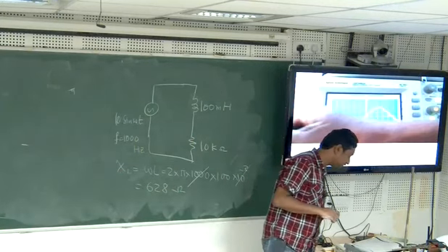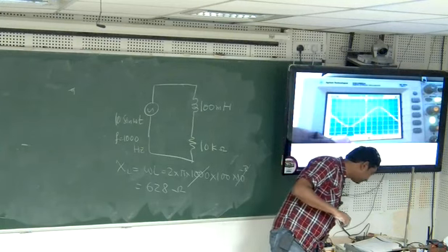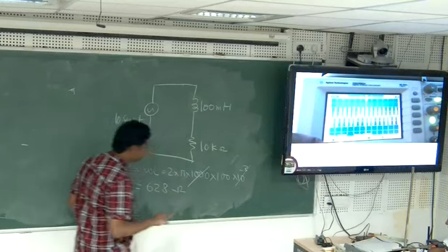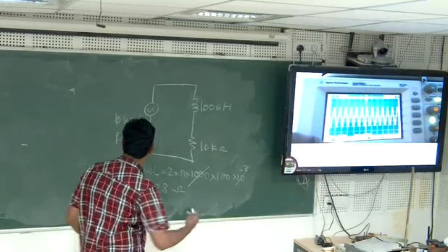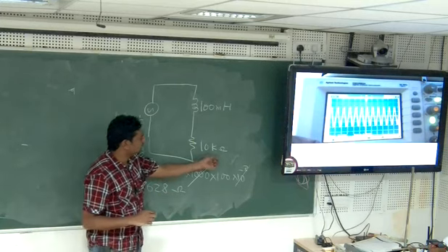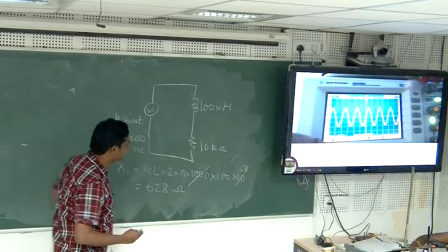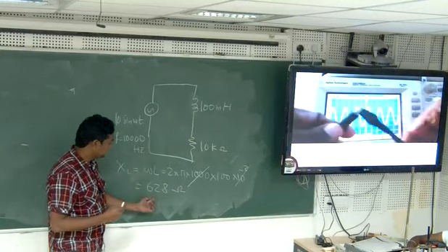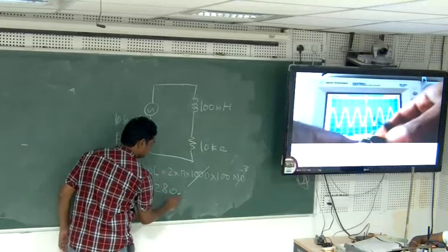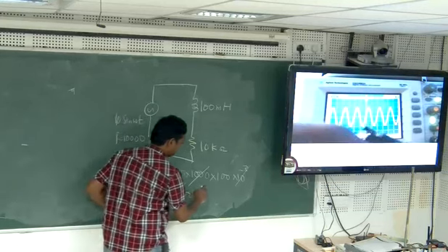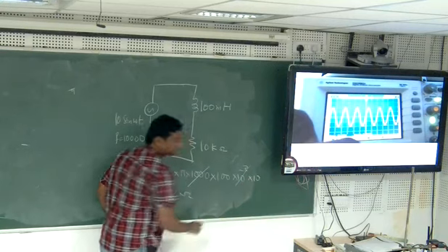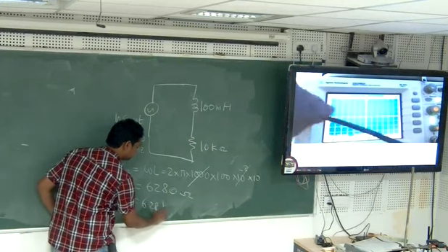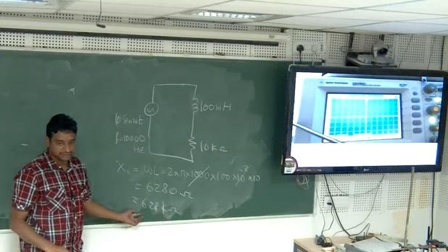So what is the frequency? Yeah, so we'll make the frequency 10 kilohertz. Okay. See, because this is 10 kilo ohms, I want something, maybe we'll replace that also. So if I make the frequency 10,000, then this will become like this. One extra zero will come. Okay. I'm putting one extra zero here. Okay. So this I can write as 6.28 kilo ohms. Okay, 6.28 kilo ohms.